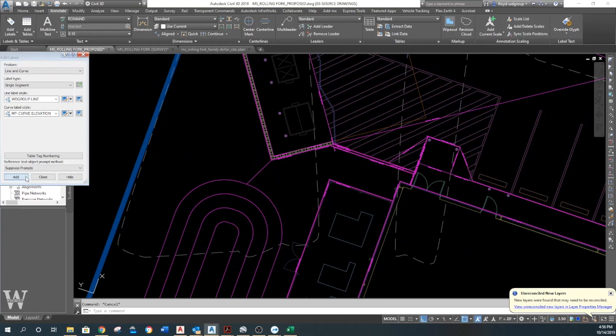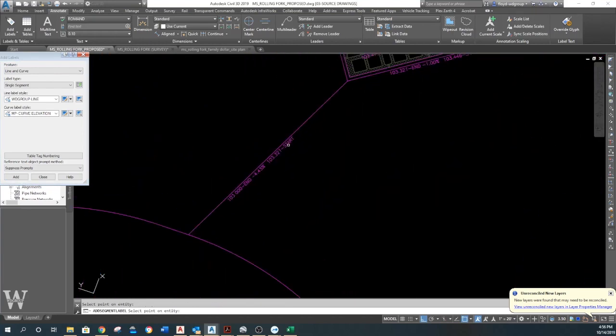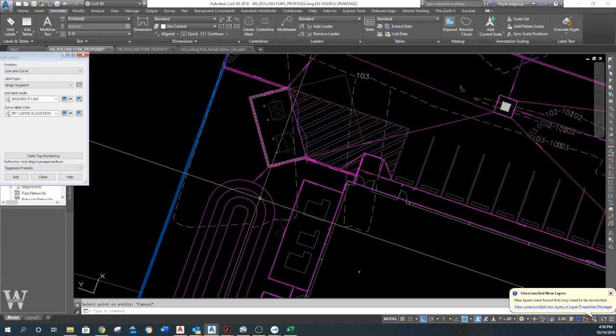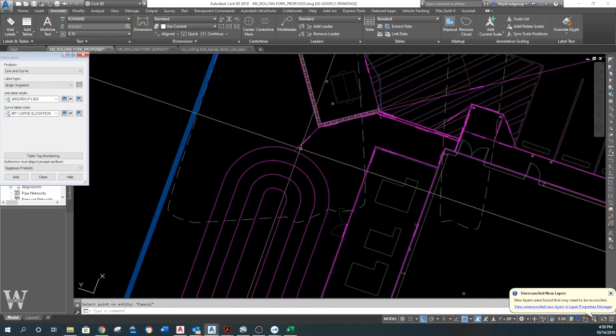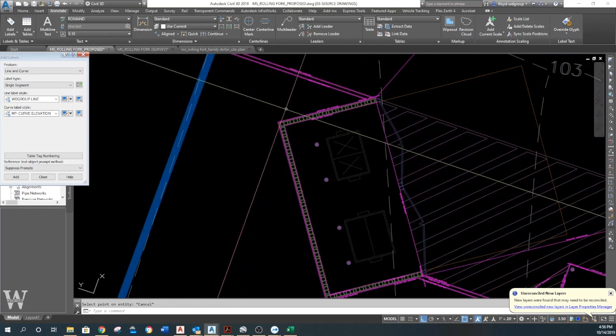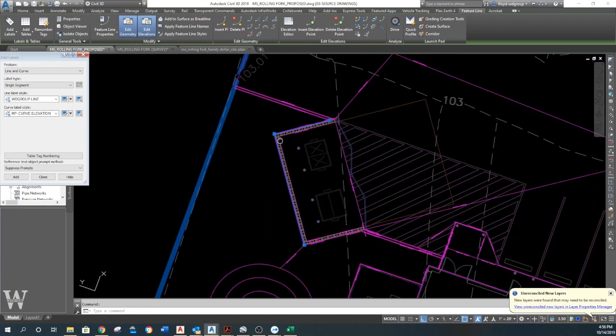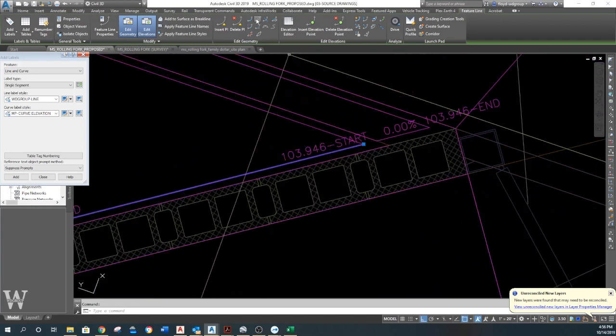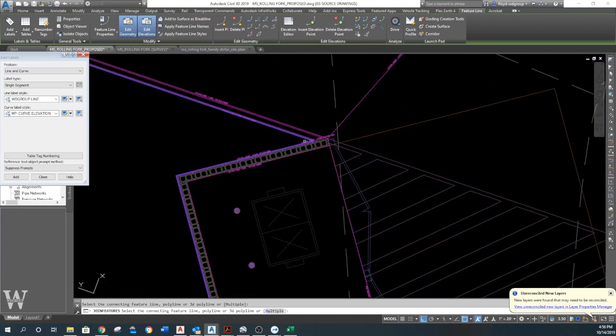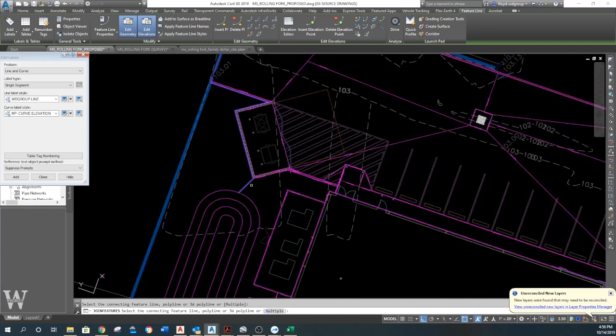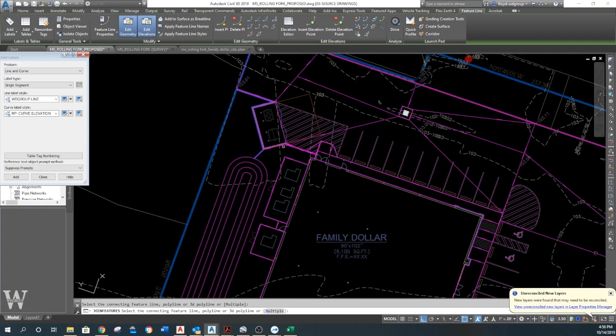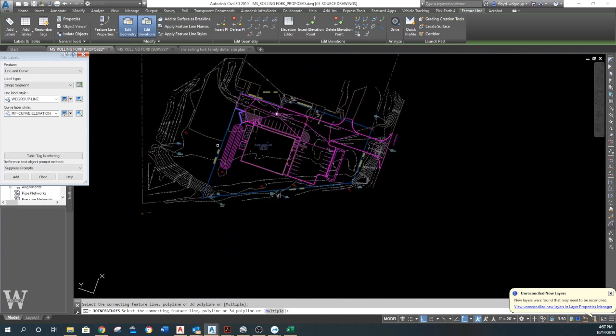Now then, this ought to look better though. It ought to be 103 too. Okay, so it slopes here. I was backing water that way. I didn't want to do that. All right, so what I'm going to do is bring this polyline from right here. I'm going to join this right there, and I'm going to join that. So I'm going to make that an outside line so I can grade to existing. So basically, I'm going to create a box around my surface so that I can tie down to the existing, because this is going to be higher or lower than existing grade.